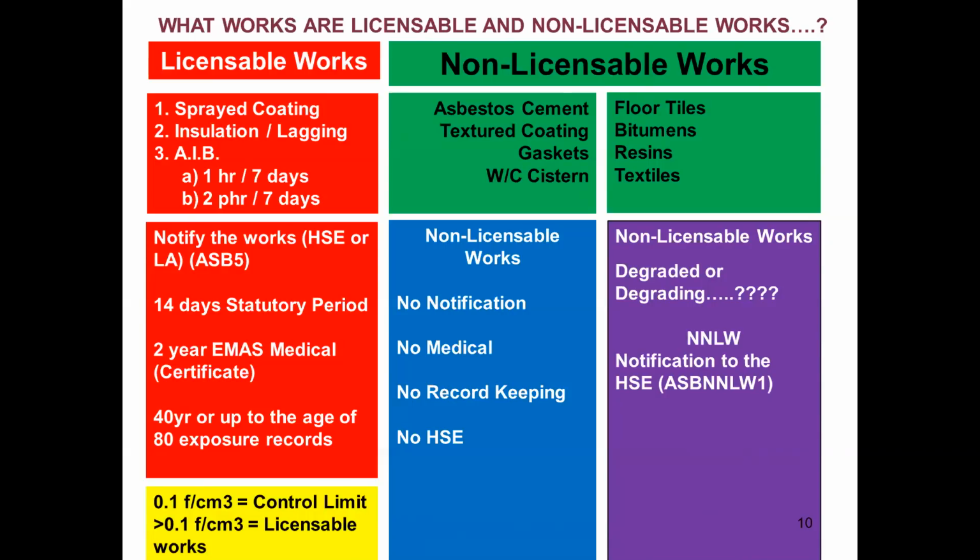Now, if the works is classed as notifiable, then of course, there is a notification. The notification form again is electronically. That is an ASB NNLW1 form, and that would be submitted prior to the work starting. There is no time in this, so there's no 14 days. That should be submitted before the work starts. So in theory, if it's an electronic form, it can be notified and then the works can commence straight away. Same aspects on record keeping as for licensed contractors, 40-year plus.